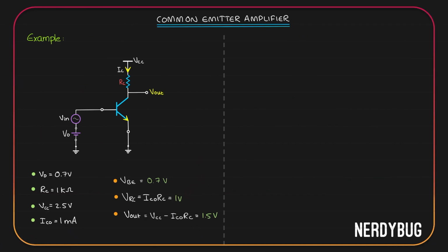I am going to apply my input signal, which is sinusoidal. I am going to call the collector current IC now. IC will be, as you know, IC naught plus the new collector current due to the input, gm V input. Assuming the input is a sinusoidal signal, let us take V input to be Vm sine omega t. Its frequency is omega, its maximum value is Vm.